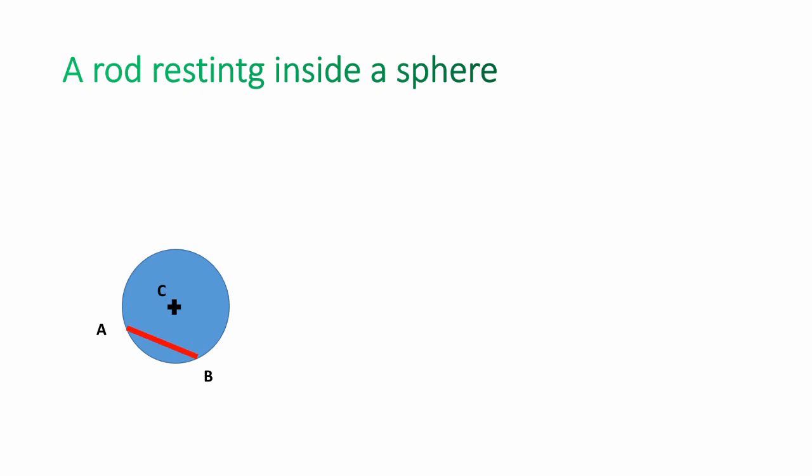In this case, the self weight is always acting in the downward direction. If I remove the sphere, automatically the rod AB is going to fall from that position. It will not be able to maintain the equilibrium condition. If you want to maintain the equilibrium position at rest, what do we need to do? I show the weight acting in the downward direction, and the reaction forces are generated toward that side. Already we have talked about the equations of equilibrium, or equilibrium of a particle. When three forces are acting, they must pass through the same point of application. Then we can say that the body is in the equilibrium position.